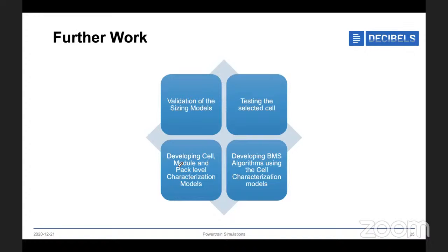And if some chemical engineering guys are responsible for developing the battery packs, from these powertrain simulations we'll get a cell, we can select some cell. Then we can go for testing the cell, doing tests like pulse characterization test, impedance test, or dynamic test.